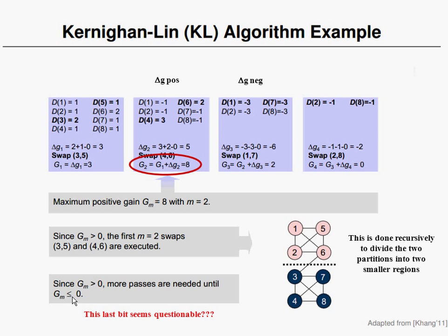But at any point, they probably meant we're referring to the delta G. Because in this case, if you find a delta G that's positive, you'll end up reducing the cost, and if the delta G is negative, you'll end up increasing the cost. In any event, this is done recursively, so the first pass would have partitioned it into these two sets of elements, and then the next time you partition these, and you partition these again.